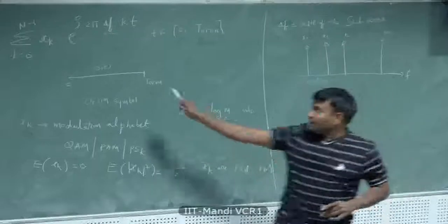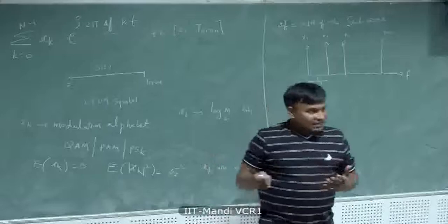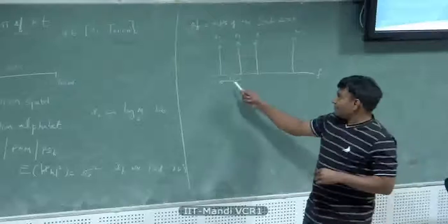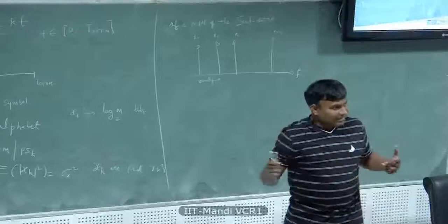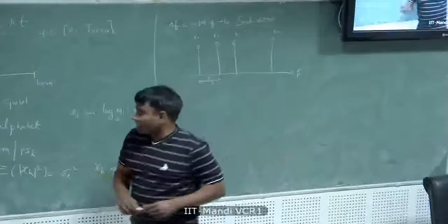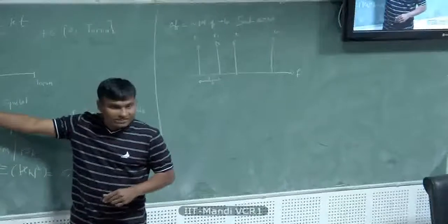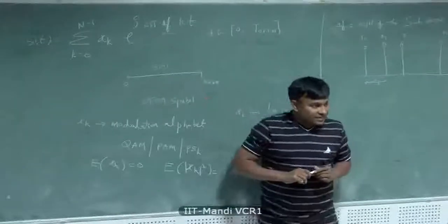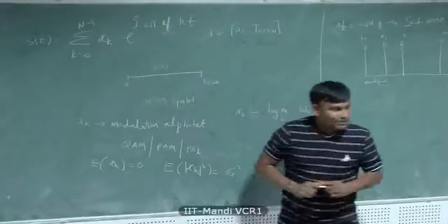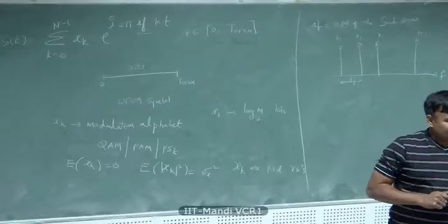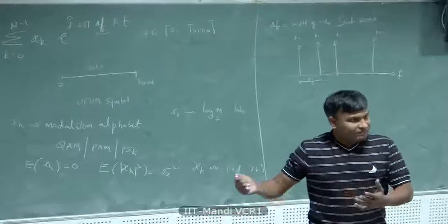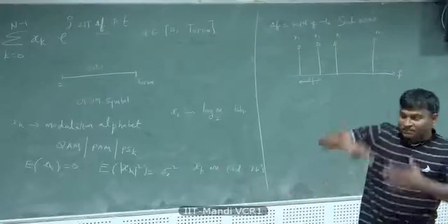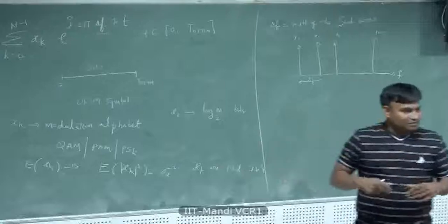Okay? You know that if you have a complex sinusoid, its spectrum is a unit impulse function at some point in frequency domain, right? But that is for a sinusoid that extends infinitely long. Whereas here, the sinusoid starts at 0 and it ends right here. And if you take the spectrum of a sinusoid which is time limited, what would you get? Just roughly speaking, it is a sinusoid multiplied with a rectangular time window, and in frequency domain, it is a sinc function convolved with a delta.